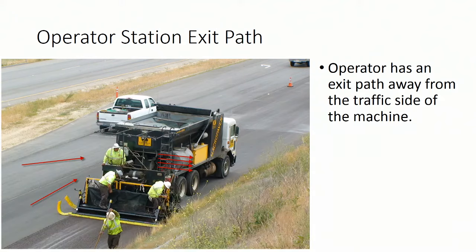And this is kind of demonstrating in a work zone where that operator, if he didn't have that exit path across the pug mill, could be trapped right on that operator station. Even if he saw it coming and had time to react, he's got nowhere to go. He'd just have to take the hit.